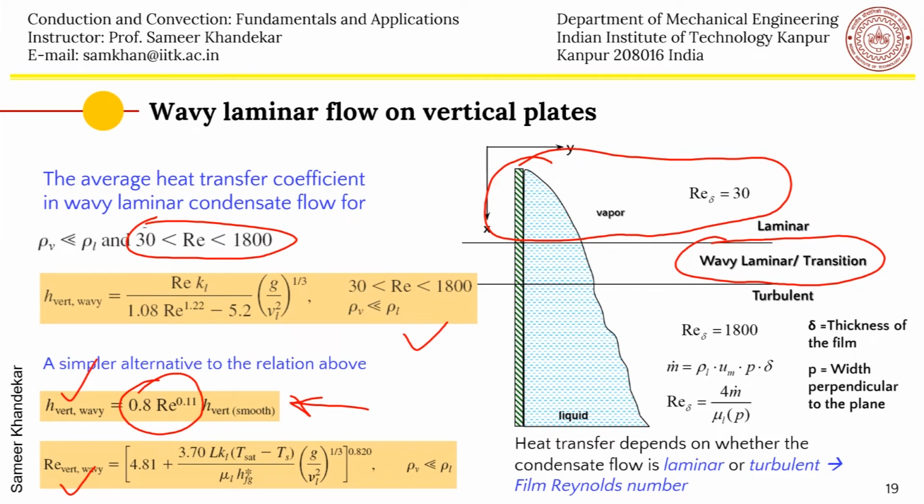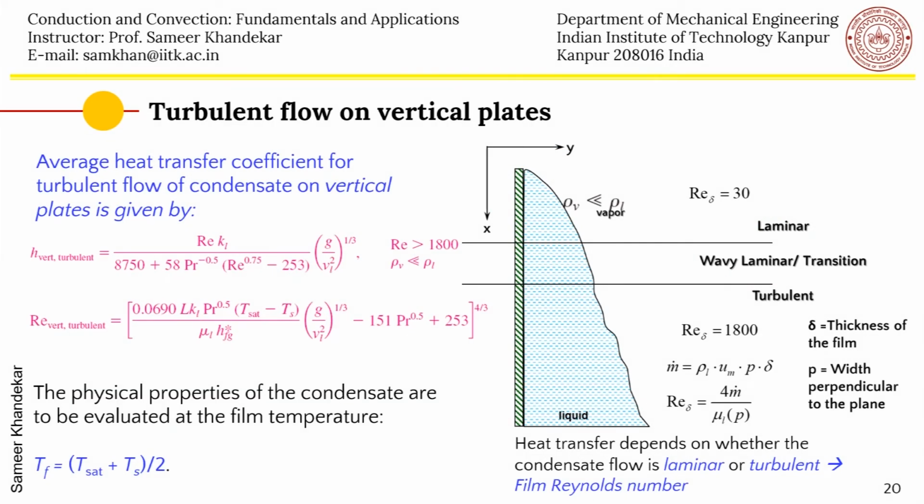These cannot be derived from first principles. These are mostly empirical or semi-empirical in nature, and one can use them for calculating the heat transfer in turbulent flows. So you can do some of the exercises which we will provide, and then use these correlations to get a feeling of typically the film Reynolds number, the heat transfer coefficients will be quite high in film-wise mode.